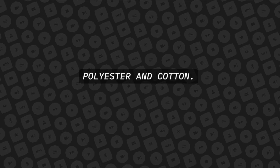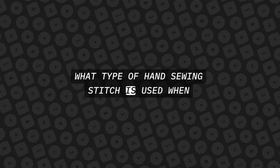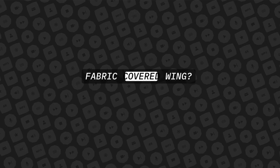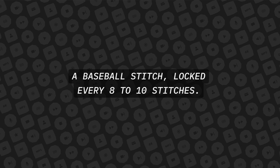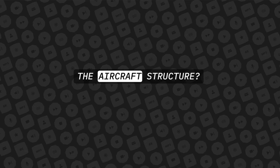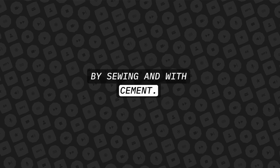Polyester and cotton. What type of hand sewing stitch is used when sewing in a panel of new fabric on an aircraft fabric covered wing? A baseball stitch, locked every 8 to 10 stitches. What are two methods of attaching the fabric to the aircraft structure? By sewing and with cement.